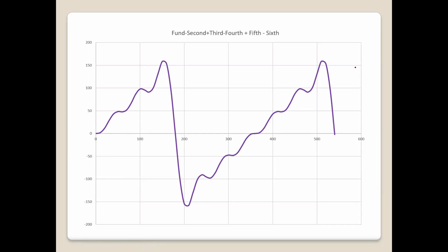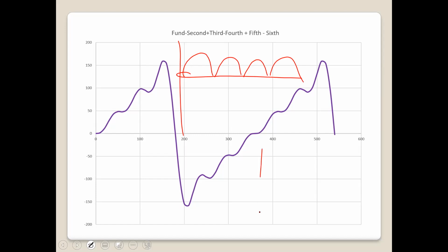And we have to use these waveforms in electrical engineering for different purposes, all right? And we may be creating some of these complex waves. The complex wave I just mentioned is of rectification. When you have your full wave rectifier, you would have gotten an output looking like that. Yes, that is a complex wave because it is non-sinusoidal. All right. If you were using a half wave, then you'll have that.